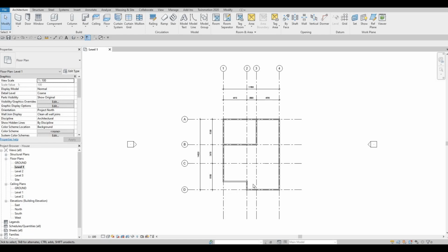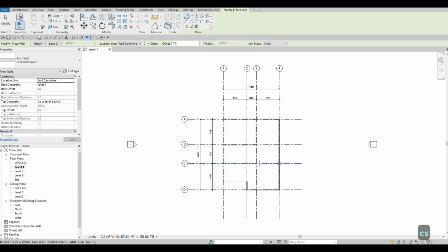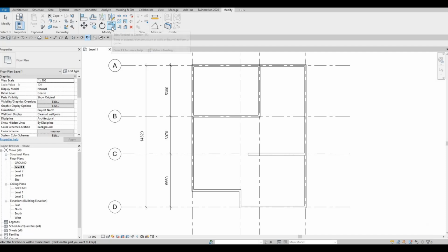One thing that I want to do is to add in the walls right here. So this will be an exterior wall again. I'm gonna select this wall, CS, that's create similar. I'm going to add a wall right here, and then from here we're going to type in TR, that's trim and extend. Basically, under modify, this is the icon for that. I'm gonna select this wall and then this wall, and then now it will be a box in. Like I said, we're going to remove this wall later on, so we're gonna leave it like this for now.